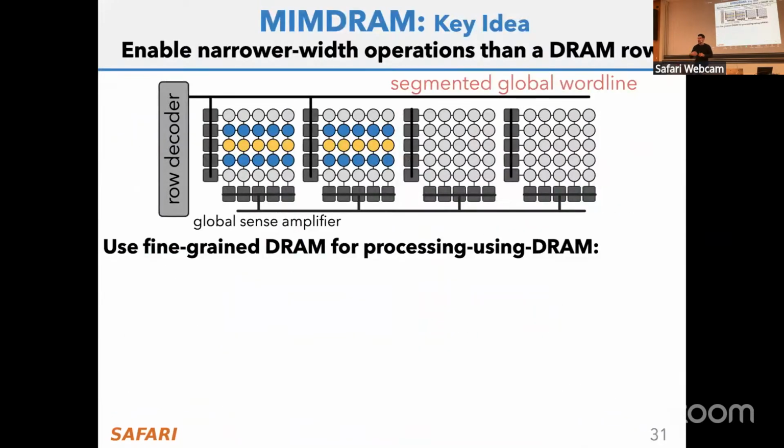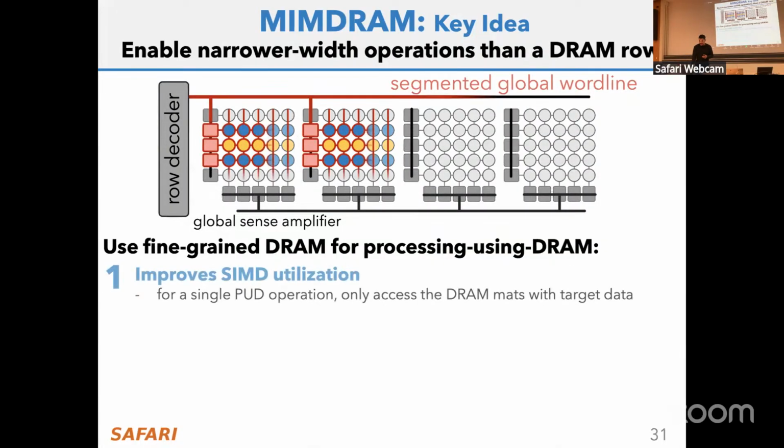We have further improved on top of these substrates to be more efficient and allow us to implement multiple structure, multiple data computation in the substrate by segmenting what's called a DRAM mat, or the many DRAM mats in the DRAM subarray, and allowing them to operate individually. Think about taking those 65,000 columns that I just mentioned and creating blocks of smaller granularities of 512 columns at once.